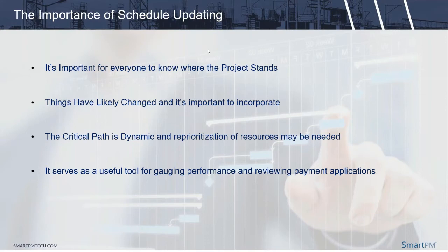And knowing that means that you should be updating the schedule, because the beauty of this program is that you're putting in all these constraints, and when you update the activities with real information, all the total floats may change. But you need to know at different points in time, based on the data and the achievement of these activities to date, what does that mean for prioritizing going forward? Not to mention, since things do change, orders happen, subs don't show up, problems come from equipment, materials, permitting issues, rain, all that stuff factors in here such that you need to potentially modify your plan.